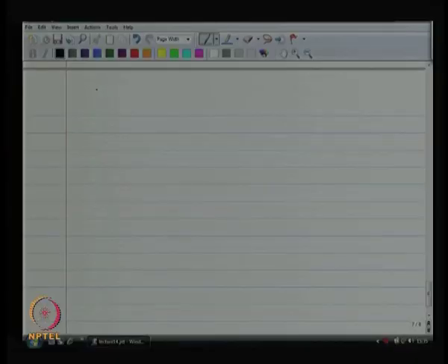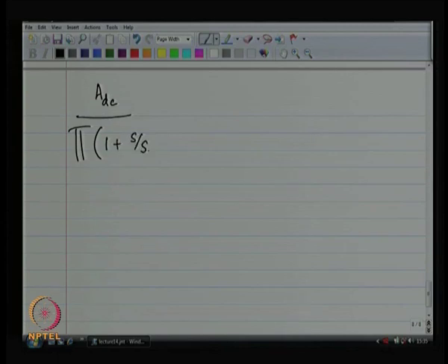So, your system is basically your DC gain divided by the product of all of the poles, right. Let us say each pole is coming from each capacitor. So, n capacitors, n poles. This is not really true, but let us say that is what happens. N independent capacitors do give me n poles.